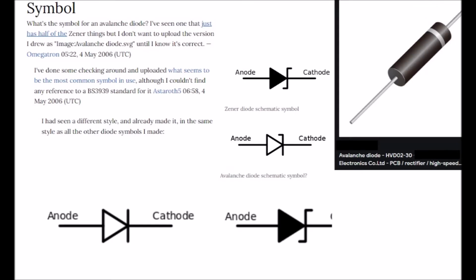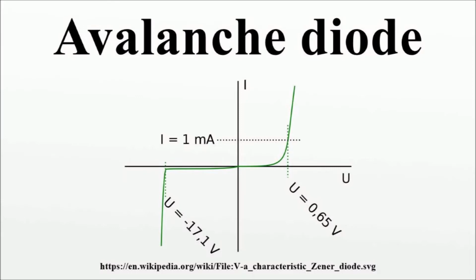The next type of diode, an avalanche diode, is another type. Granted, many types of diodes have ratings for an avalanche breakdown. An avalanche diode is a diode that is designed to experience avalanche breakdown at a specified reverse bias voltage. The junction of an avalanche diode is designed to prevent current concentration and resulting hotspots, so that the diode is undamaged by the breakdown.